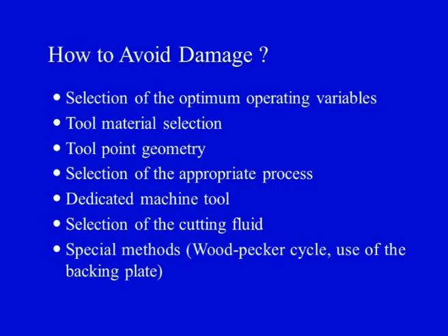Selection of the cutting fluid is another issue which we have seen. In certain cases, because of the drilling action, the matrix may burn because of the high amount of heat generated. Although a lot of heat is not generated in drilling of polymer composites, in some cases, if the feed rates are very slow, the drill is in constant engagement with the material for a long period of time, and matrix burning may take place.